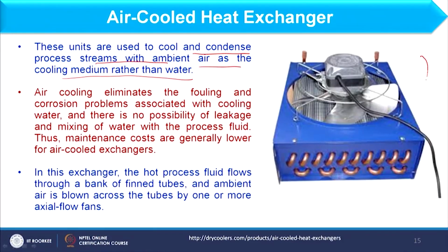If you see this schematic, when the fluid is to be condensed, that fluid should flow inside these copper tubes. And this fan we are using to throw the air over these tubes, and therefore the vapor which is flowing in the copper tubes can be condensed, and the hot air exits from the bottom.